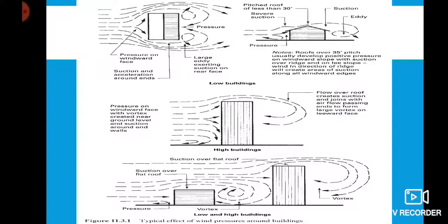Wind striking the exterior walls exerts a positive pressure on the wall, which forces air through openings and into the interior of the building. At the same time, the windward wall is receiving positive pressure. The side and rear walls are receiving negative suction pressure. Therefore, air within the building is being pulled out at an opening in these other walls.